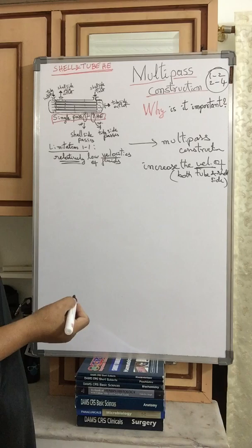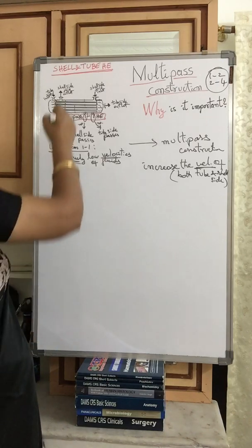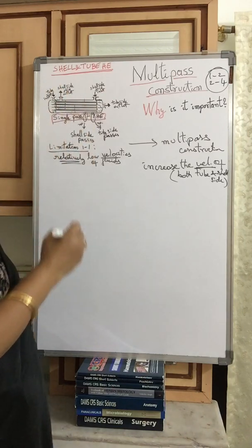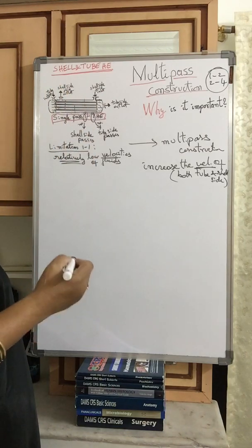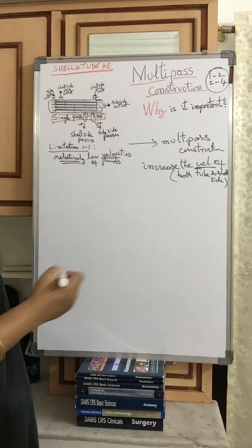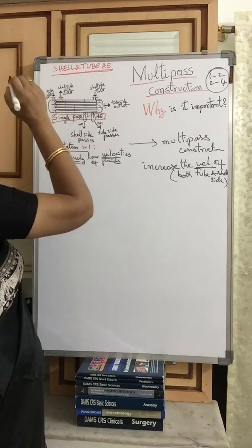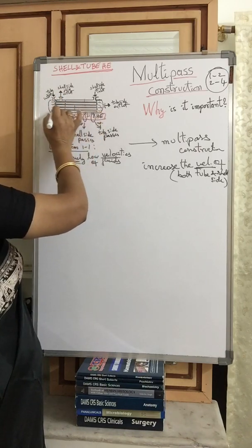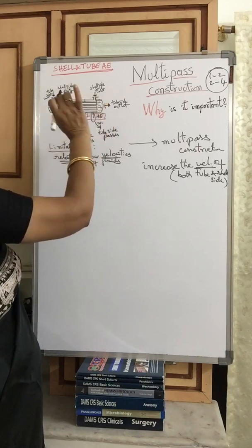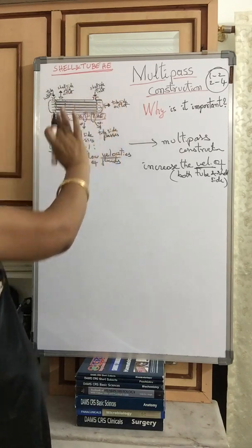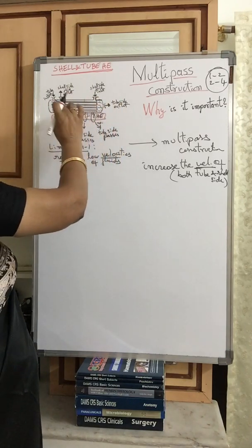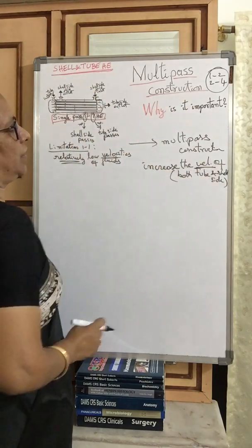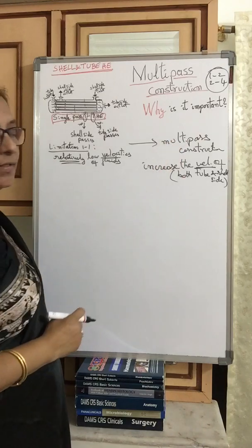That means pumping costs will increase. If we simply pump the fluids at higher flow rates, operating costs, pumping costs will increase. So without changing the pumping costs, and without changing the length of the tubes, number of tubes, or anything else in this design, how do we modify it to get higher velocities of the tube side and shell side fluids?